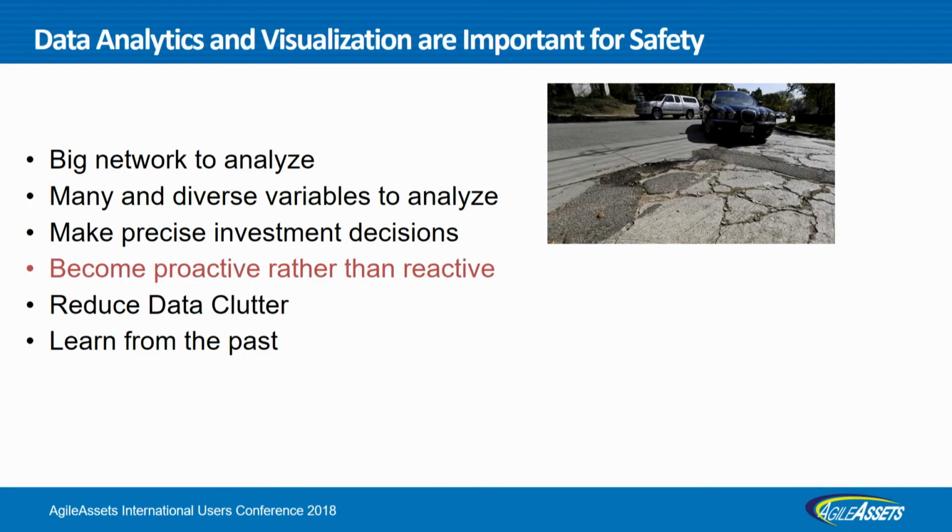We have to be proactive rather than reactive. We cannot wait until all my systems are falling apart and we're not investing anything. So from that perspective, we need to have some predictive capability so we know the condition of the road, and from that we spend our money and become proactive. So even though there is no crash on a stretch of roadway, we can try to improve the condition of the road and identify any geometric deficiencies so that we become proactive and can save a lot of money.